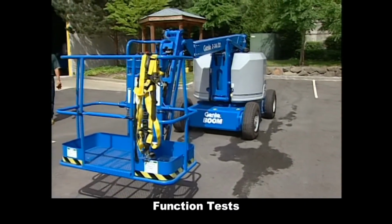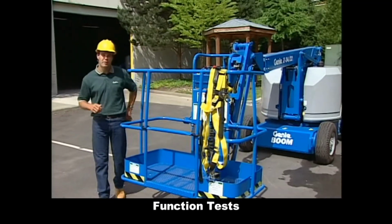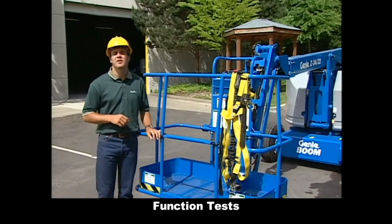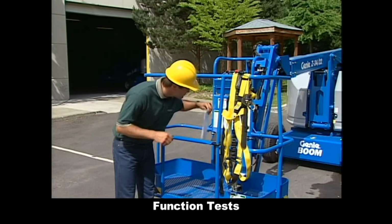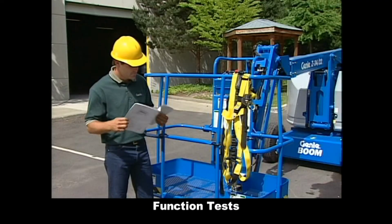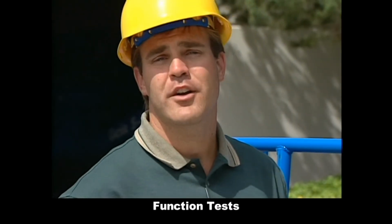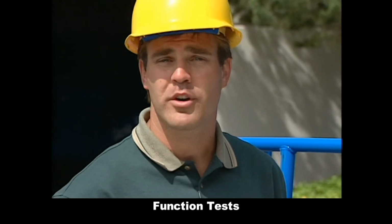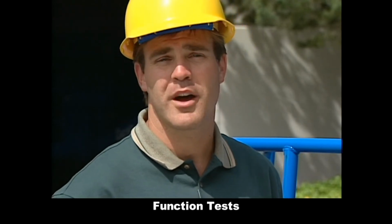Now, before you begin testing functions, select an area that is firm, level, and free of ground and overhead obstructions. Follow the testing sequence listed in the operator's manual. If a machine fails a test, it must be removed from service, repaired, and re-inspected before it can be used. Let's take a look at a few examples of function tests that apply to aerial platforms.